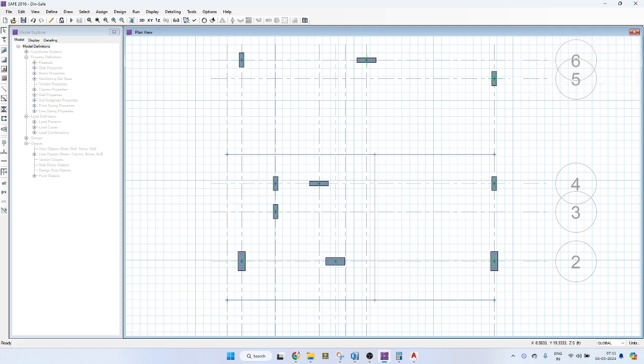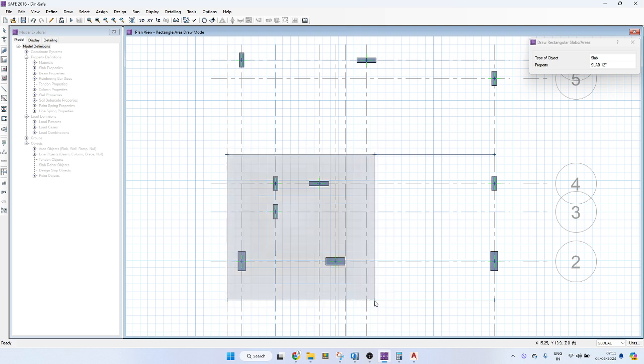So you've got one particular grid line, like a helping line. You'll click on slab and draw slab now. See, you've got 4 different points, you've got the slab. And now what you'll do is delete these lines. After you draw once for everything and once you're completely sure, you will delete this line, because these lines are not necessary and are not going to participate in anything. Just for you to draw the slab, we have created this.